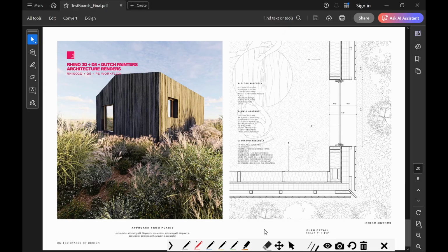And then you're going to have your exterior rigid insulation, right? This is your permanent insulation, and then your membrane, your air barrier, or excuse me, it's like your air barrier, vapor barrier, but that terminology can get very confusing for people. So I'll just call it the weather barrier or the weather membrane. And then your sheathing, and then your framing, and your interior finish. And so I'm going to transition over to my 3D model so you can see it a little better.